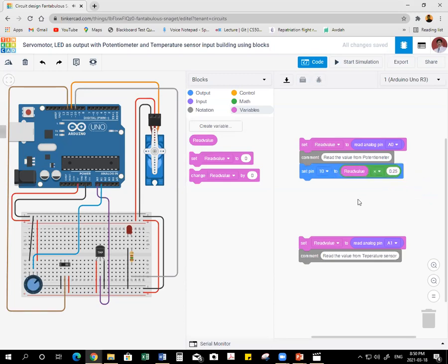Now what are we doing? This is from the potentiometer. Now this potentiometer I will put as 10 kilo ohms, let us take. Now it will vary from 0 to 10 kilo ohms, but whatever it varies from 0 to some X value, the A1 pin will get from this potentiometer a value between 0 and 1023.